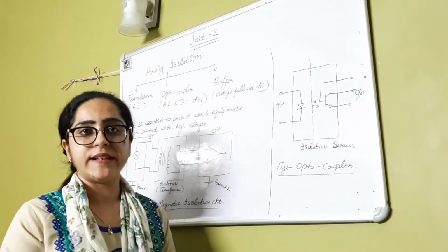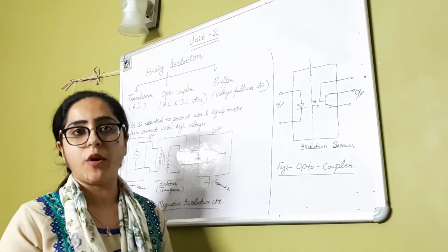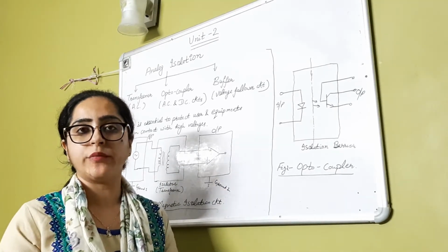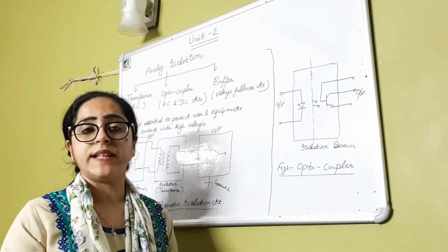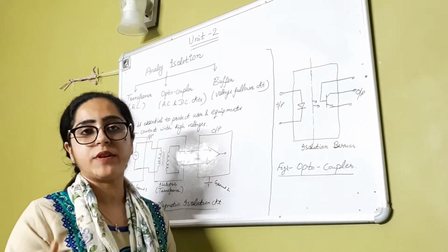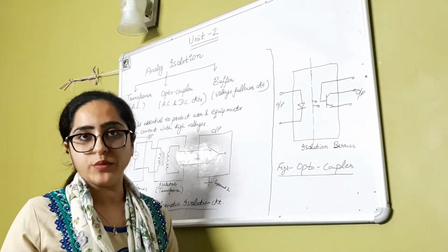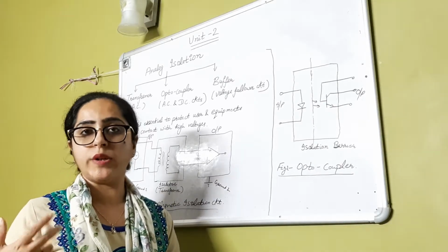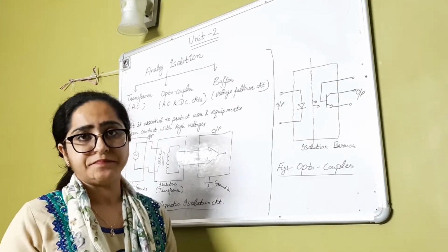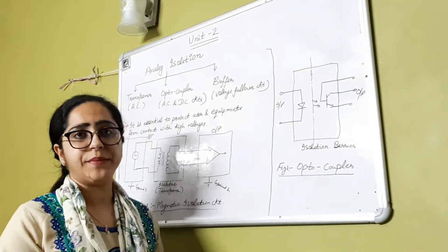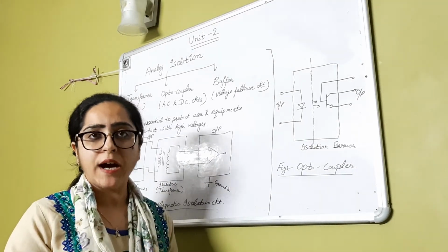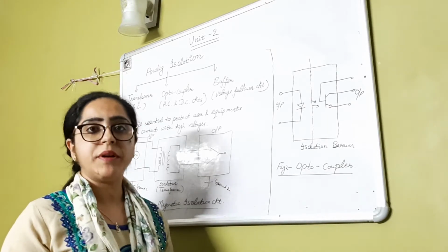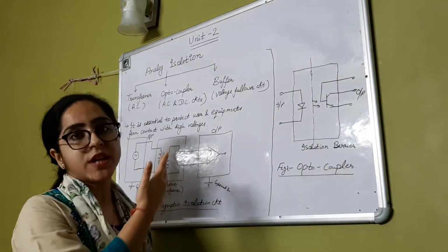Once all the hardware components along with the DAQ system are connected, through this DAQ system it is further communicated to the computer or the laptop, from where the monitoring or controlling operation can be done. For that purpose, it should not harm the computer, it should not harm the DAQ system. For that purpose, isolation is very much needed.